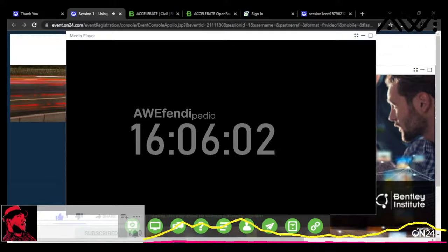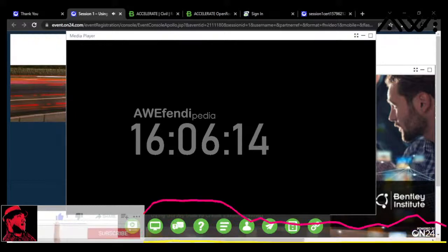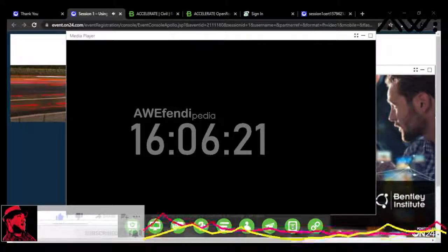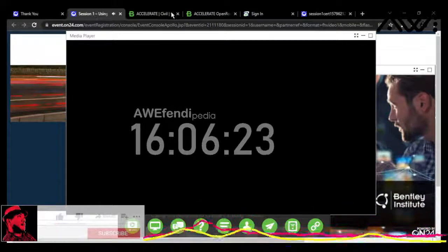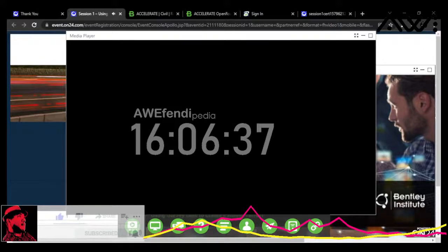I can see that in my file 3, we brought in 2694. It's a traverse point, and here's its XYZ, and I can see that it matches up almost exactly with the shot that was taken in 4. So I'm good to override it. If I go back to my option, I can say they were just doing a check shot, or they were reshooting the traverse point, so I'm okay to override it. The differences in the XYZ were negligible there. It's going to go through every duplicate feature and make sure that it understands what we want to do with it.